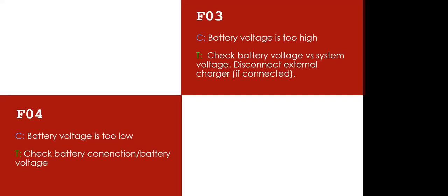And the inverter is reading that your battery is sensing about 40, 42. The inverter will not recognize it as a voltage to come up on, because what you set on program 28 is what the inverter will act on.